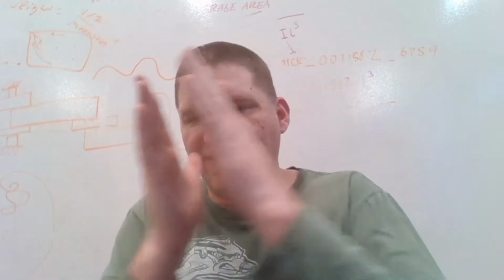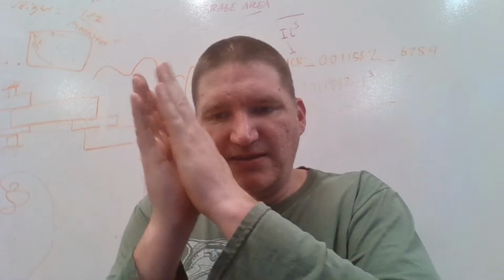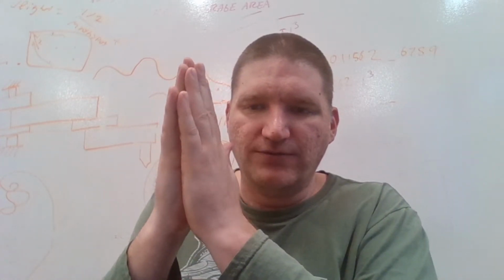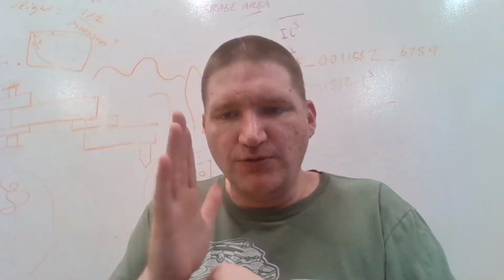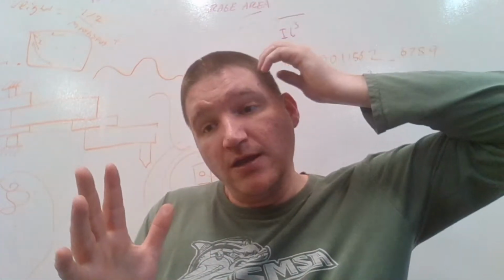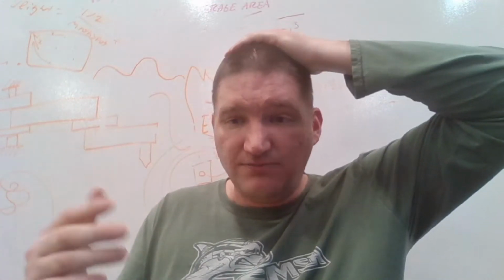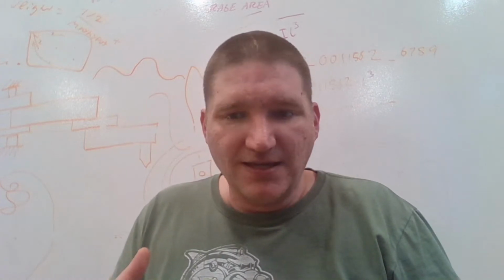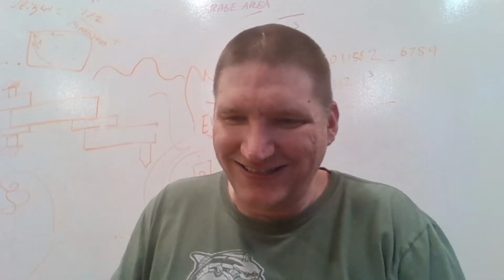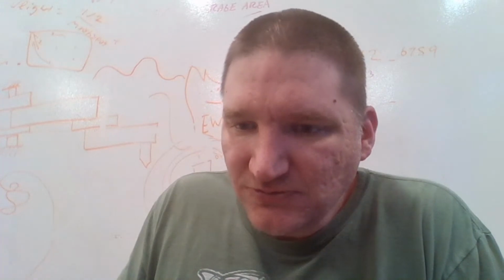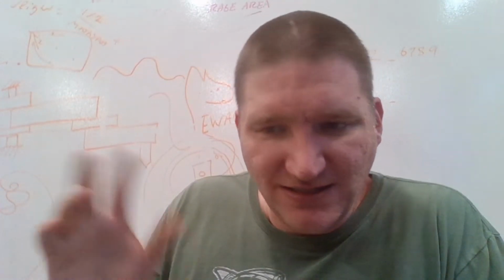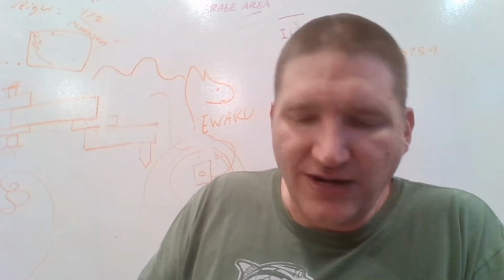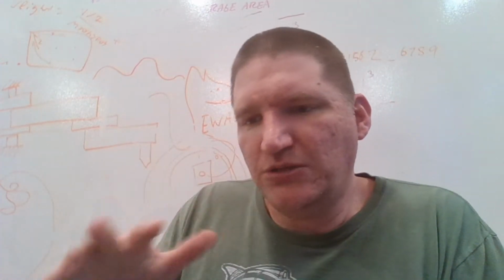For the original MonoRail, right now I have a 30-degree angle, but if you reduce the angle to like 15 or 10 or 5 degrees, you could move it less to change Z more, and you could gear it down and get more Z. But the more you do that, the more you lose Z resolution, and you don't want that. So I think 30 is a happy medium: you get about half the resolution as if you were driving Z directly. So half is pretty good.